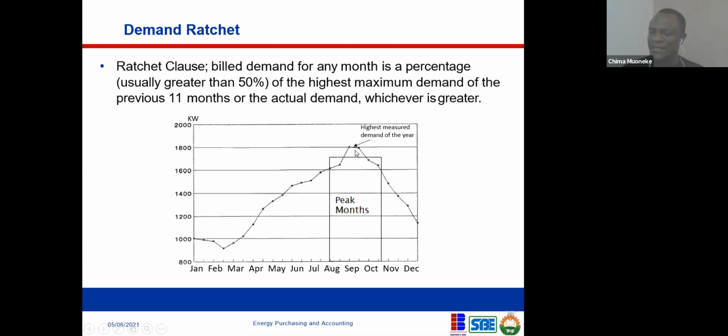That will be your demand charge. For this customer, assuming that this profile is for 1 month, they're going to charge you 1,800, which is your peak demand, times 5. And that will become your demand charge for that month.